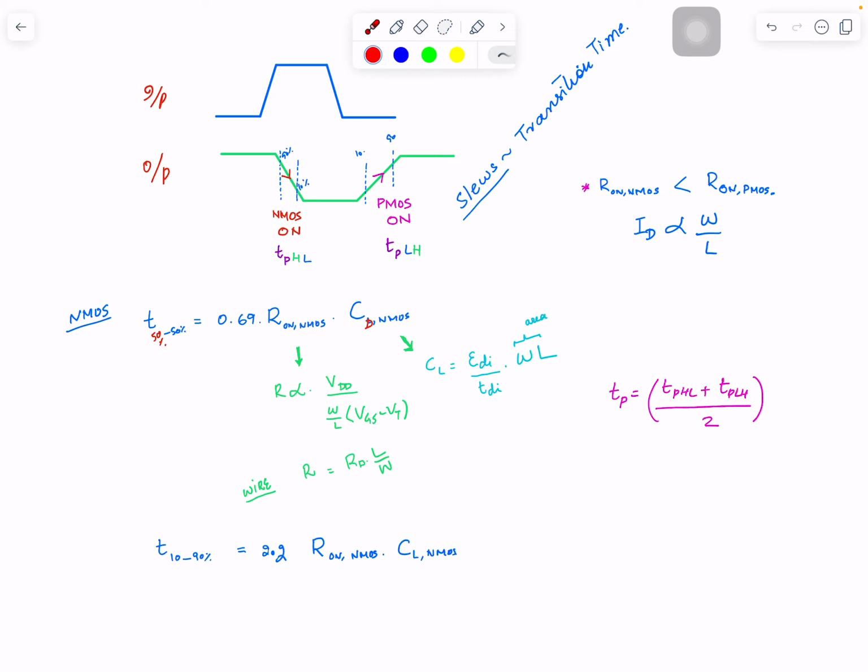And if you increase the width of the transistor, if you use bigger transistors, higher drive strength cells, then you will have low resistance. Typically when you pick a different AND or NOR or inverter, you say, okay, I need a high drive strength because their resistance is low, and as a result their delay is low. It depends on which parameter you vary and which will swing more.